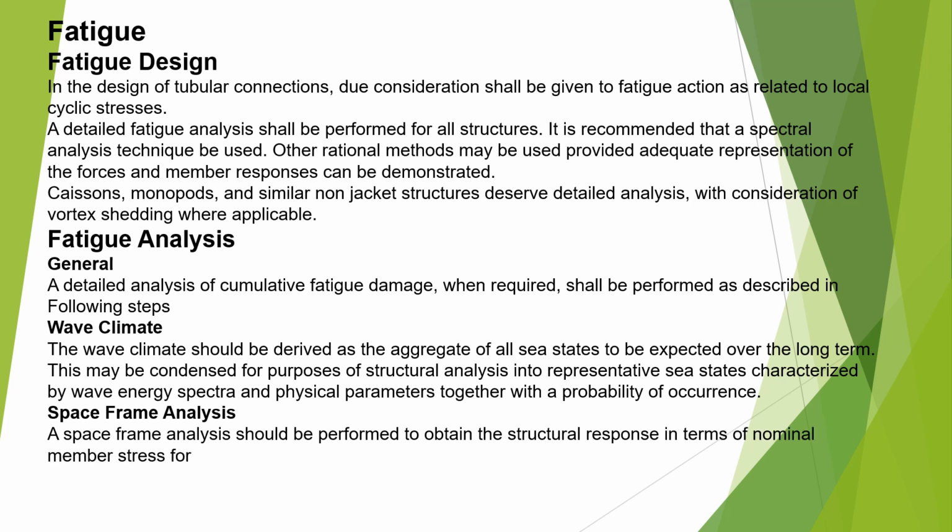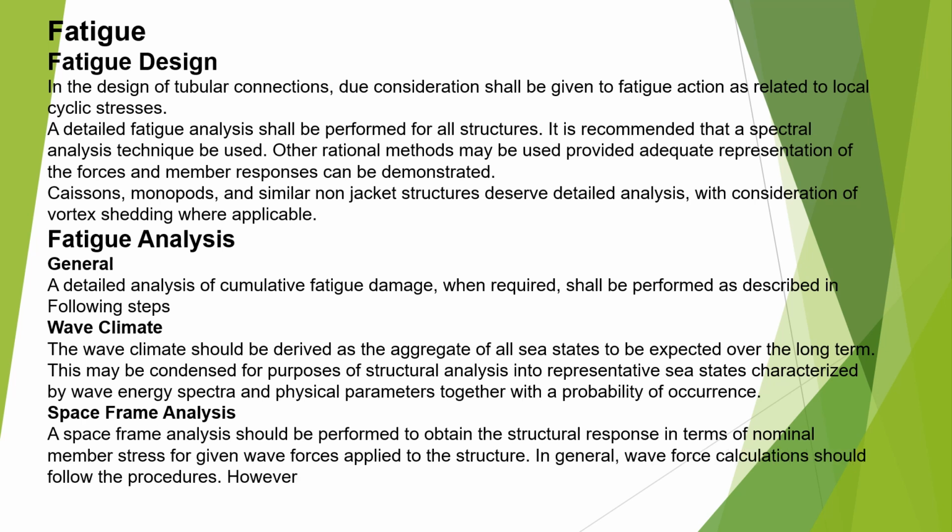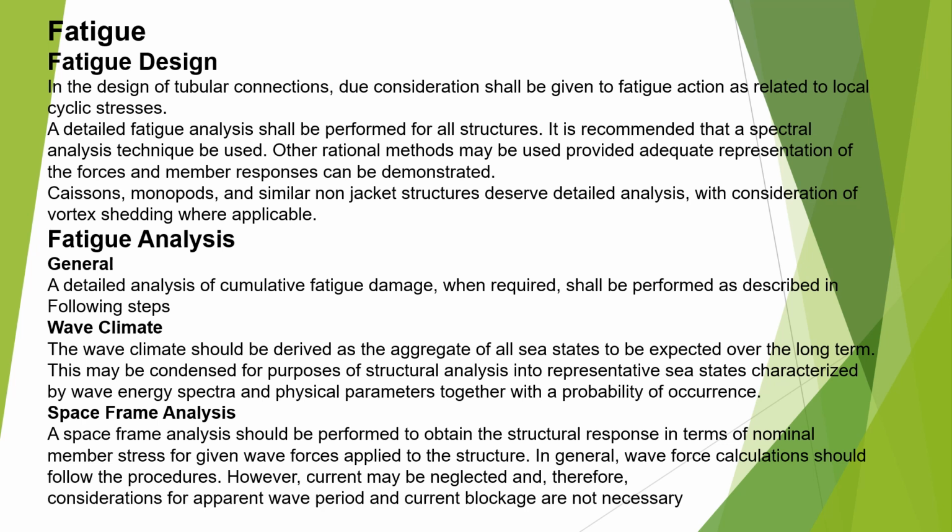Space frame analysis. Space frame analysis will be performed to obtain the structural response in terms of nominal member stress for a given wave force applied to the structure. In general, wave force calculation should follow the procedures. However, current may be neglected, and therefore consideration for apparent wave period and current blockage factor are not necessary.